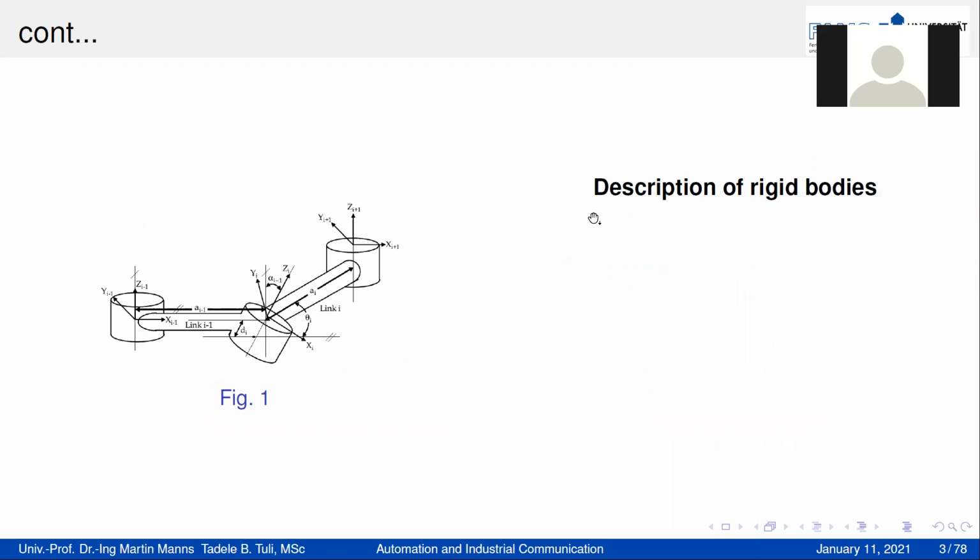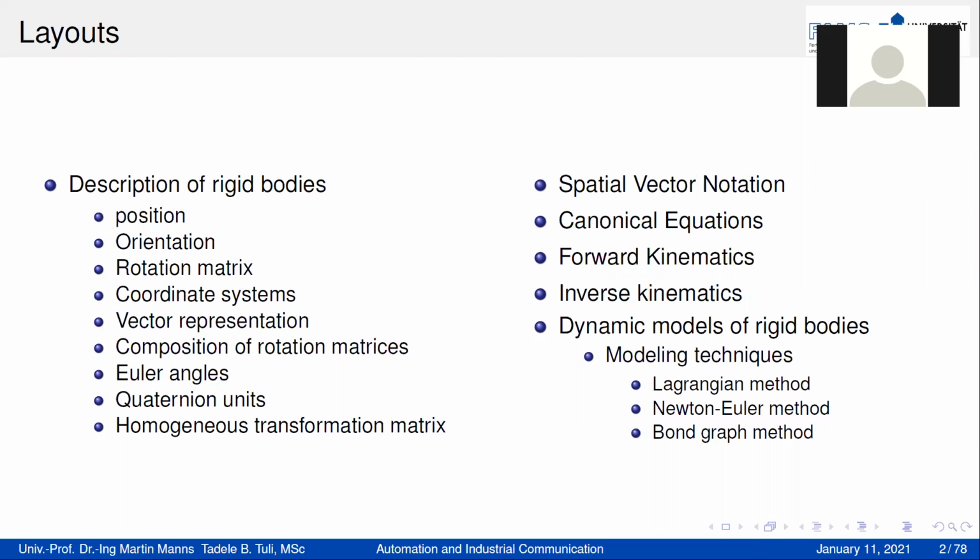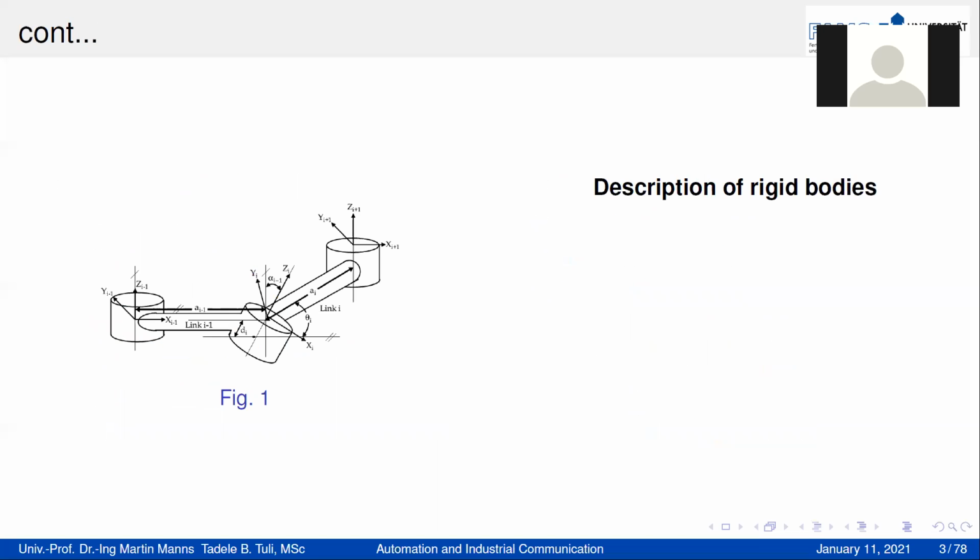The other point is that whenever we talk about rigid bodies, because a robot is a rigid body, we can talk about the description of these rigid bodies in terms of 4 parameters. These 4 parameters in robotics, we call the Denavit-Hartenberg notation. These are link length, joint angle, offset angle, and offset length. Actually, we are going to see this in detail later on.